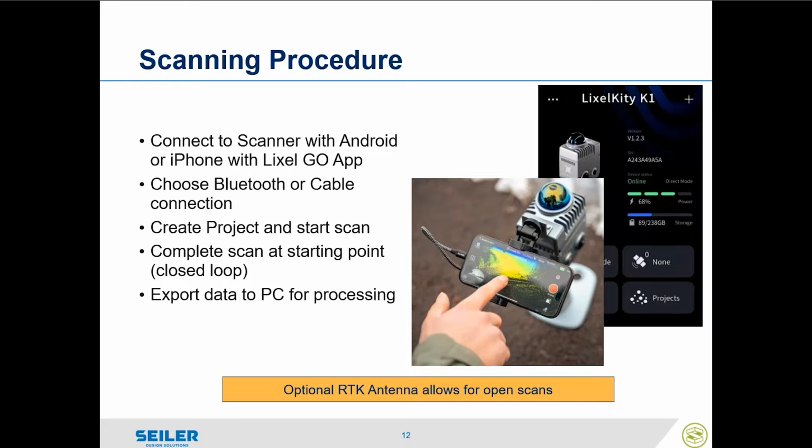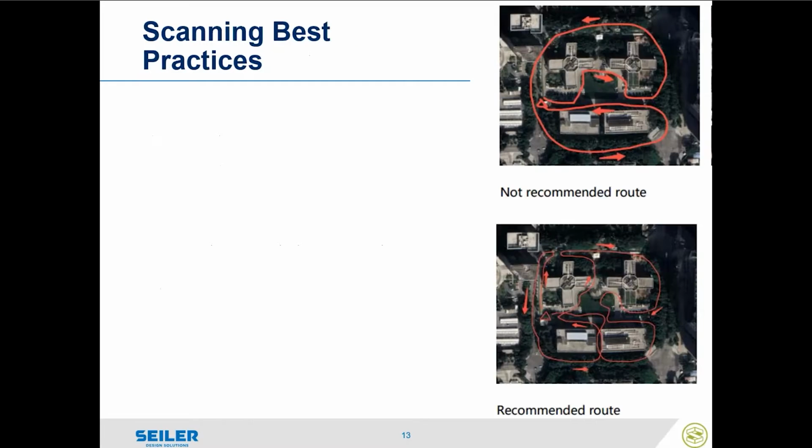The unit also allows for ground processing, ground control points. So you can set this on a known target. If somebody's gone ahead and surveyed control points throughout your site ahead of time, you can actually incorporate those points into your scan to help with both a correction and a local site calibration. So if I was on a local coordinate system, I may have a local XYZ for column lines or points or other key control features. I can incorporate those into my scan to make sure that my scan fits into that proper coordinate system.